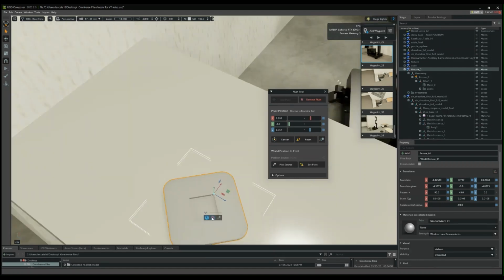After fixing my pivot, I would then move on to my snap tool. So I would click on the snap tool to activate it and check what all features are ticked. I see my edge and my surface and my vertex are ticked, so that's good enough. So now I'm going to move this over here. Perfect. Now this particular plate has snapped to that edge.